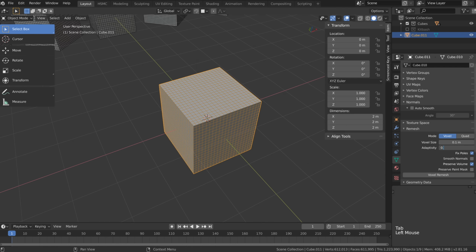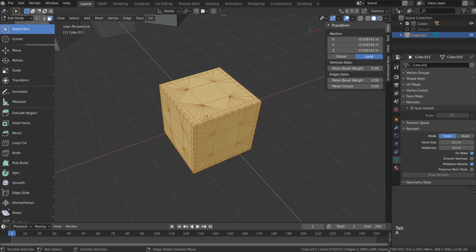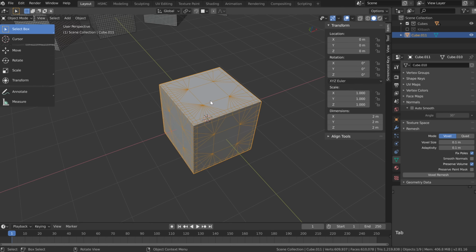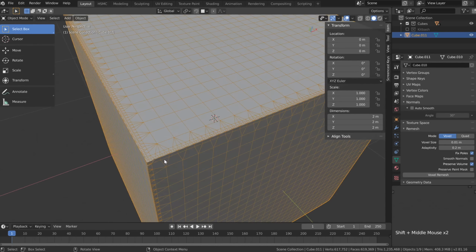And as soon as we try and add some adaptivity into this and try again, we can see in the center of the faces we've barely got any additional polygons there, and our poly count for this cube now is under 1,000, so 4 times less. I'm going to drop this even lower, 0.01, and drop this higher, 0.2, and see what we get. And now we've got quite a lot of geometry right where the faces are turning corners.